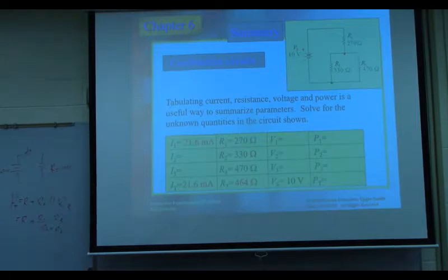See, this one is here. Definitely here you can calculate this R current 1 and 2 and 3, but that's not the best way. Once we know this current here, can we calculate the voltage here? Yes. So how to use that? V equals IR. Current times resistance. So this value times this one equals what? 5,800. Okay, 5,000 something millivolt. So 5.82. Perfect. What's next?